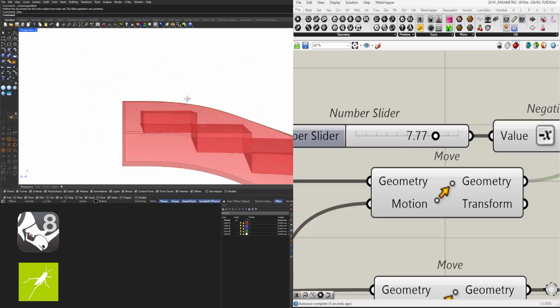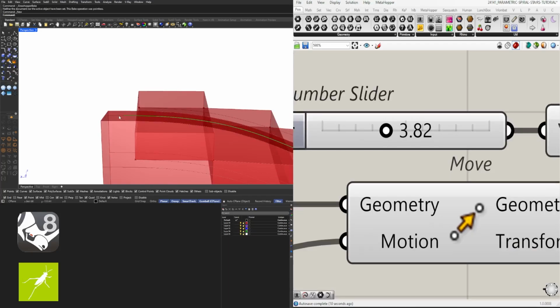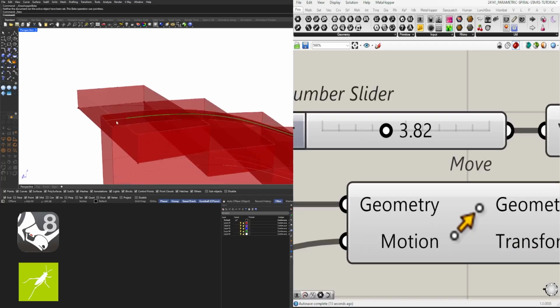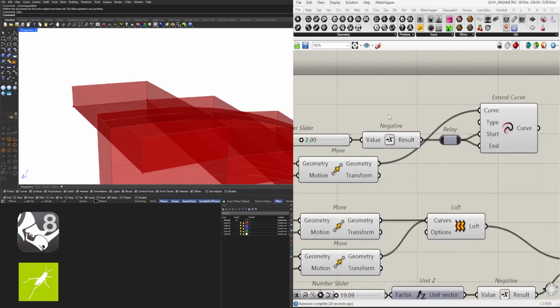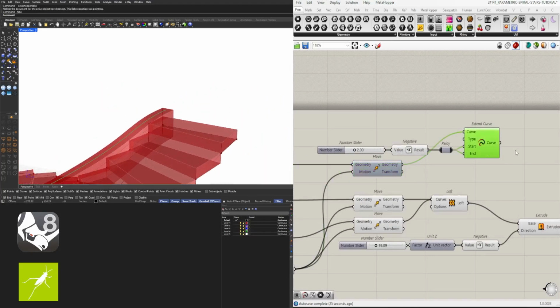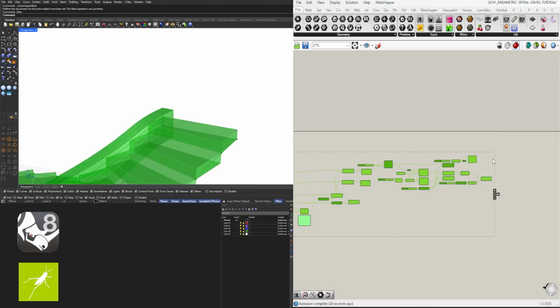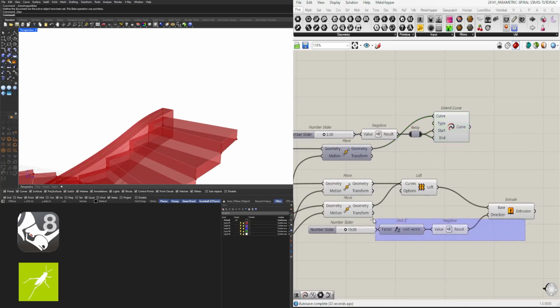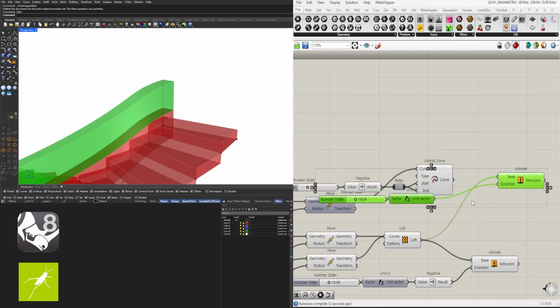And this will help so that the railing sits right on the stringer here. Rather than it sitting right at the edge, that sometimes creates a conflict. And it also gives us a little bit more control here. Now we're going to take this and extrude it up. So I'm copying that extrude and overwriting the input.